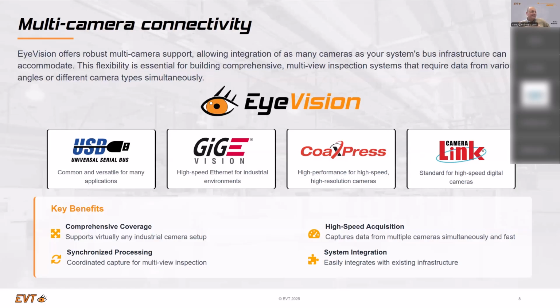Let's say for the majority of applications, like standard machines, the 1 gigabit GigE Vision is enough. And of course, today you can get 2.5 and 10 GigE cameras, and there are some new ones upcoming which are faster. But in many cases, if you have very high resolution and very fast cameras, CoaXPress is right now the choice you have to use.